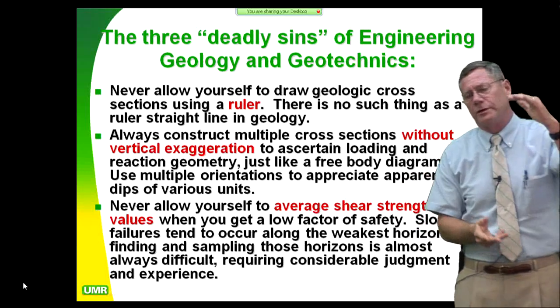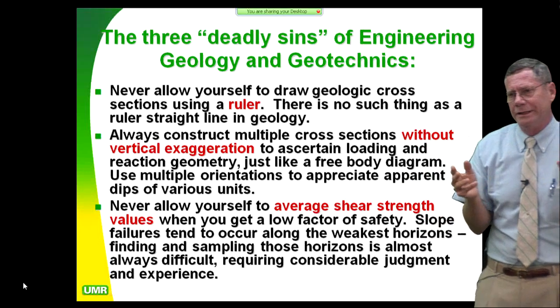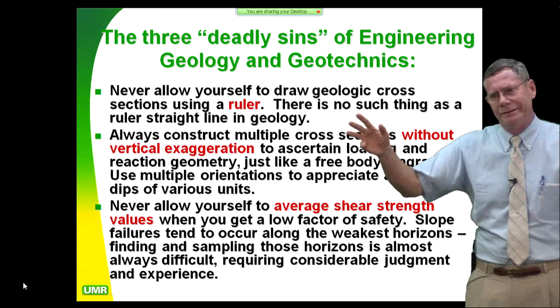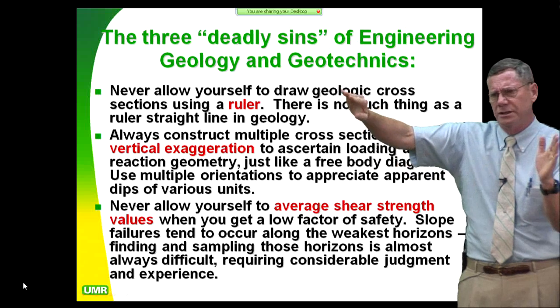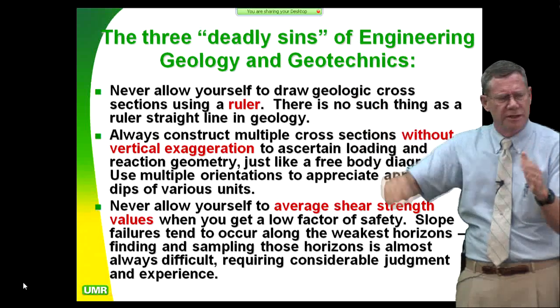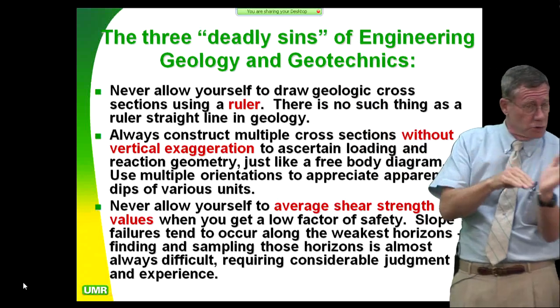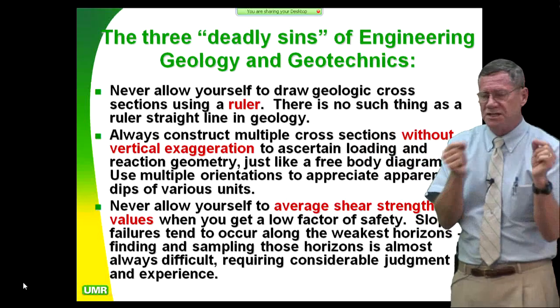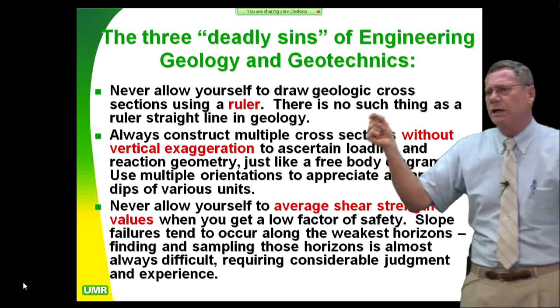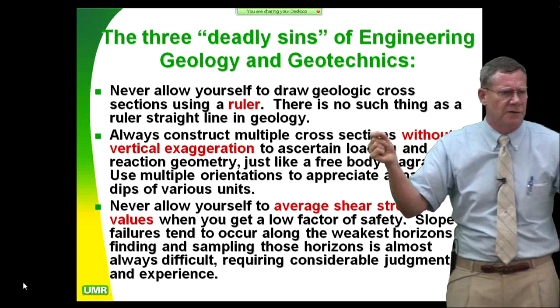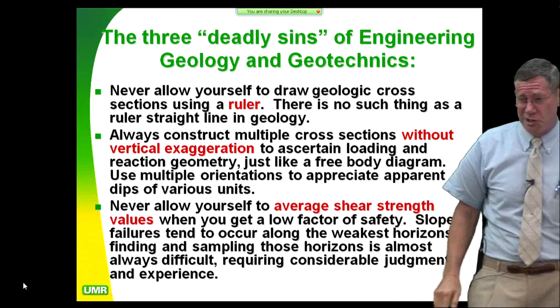If you had a 3-to-1 vertical exaggeration and you divide everything by 3, you're not seeing it like it really is. You need to draw the passive wedge, the log spiral shape of it, the Coulomb solution. You need to draw the active wedge to see where they are physically. This becomes of critical import when you start designing stuff next to channels and on hillsides.